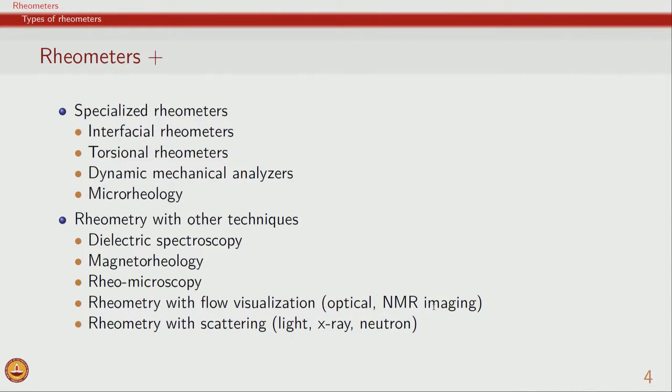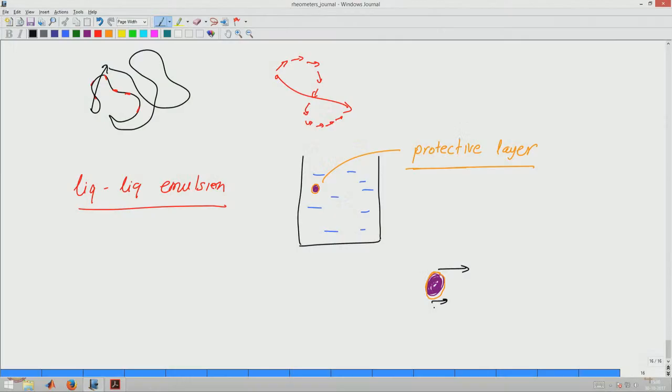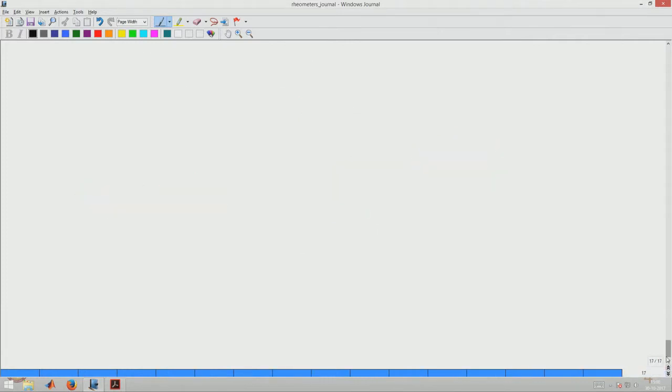And then another important aspect of rheometry in the last 5-10 years has been that we do not assume the flow, we actually examine the flow that is happening. For instance, we have been always saying that between two parallel plates, if you take the fluid, right, and we assume that because the top plate is moving at a certain velocity, we will have a linear velocity profile.